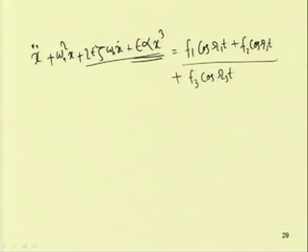But when we have this nonlinear term in this equation, we cannot use the superposition theory and one has to find the response for each case. That means one has to find the response of the system first for f 1 cos omega 1 t. So, one has to find the equation of motion by considering all the effects.